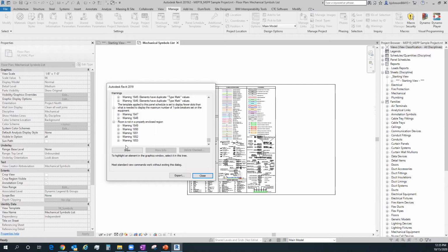That can cause more problems, especially even in linked files like the MEP guys. You may not have a problem in architecture whatsoever, but the MEP suffers at that point because the model's not quite closed up like it should be. That causes problems in spaces, having MEP's room names show up correctly, things like that. So usually when we find those rooms not in closed regions correctly, if I'm in SD, I don't usually care, but as soon as I get to a DD phase, I want those to be cleaned up as much as possible because other team members are going to have issues with it thereafter.